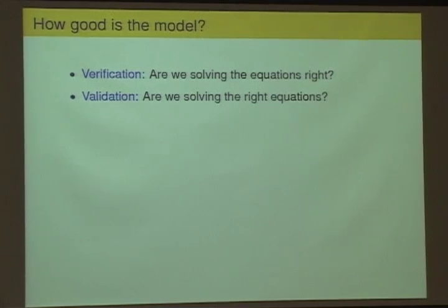So as I said, models are never right, so we have to be skeptical of any results that come out. And so a big question to ask with any sort of modeling of this sort is, how do you know your results are at all correct? So there's verification and validation that we have to pay attention to, which these terms are sometimes defined as, are we solving the equations right, and are we solving the right equations?